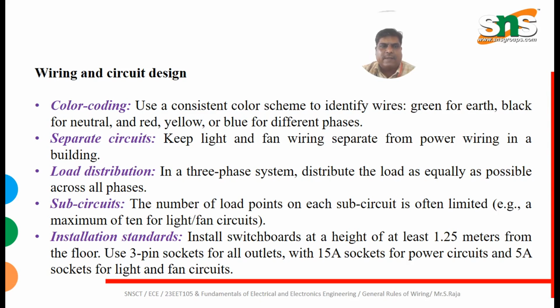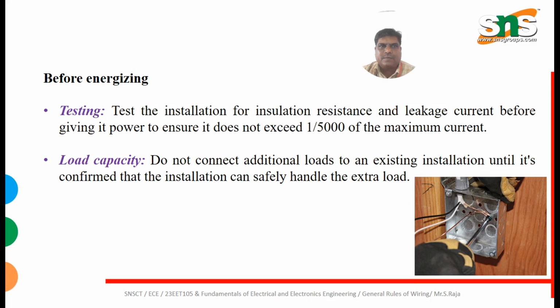Installation standard: install switchboards at a height of at least 1.25 meters from the floor. Use 3-pin sockets for all outlets, with 15 ampere sockets for power circuits and 5 ampere sockets for light and fan circuits. So these are the standardized ways of making circuit connections.